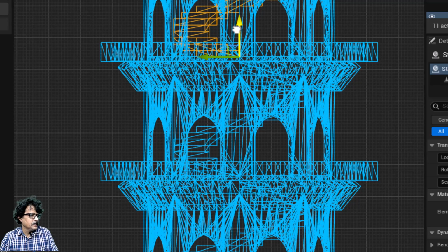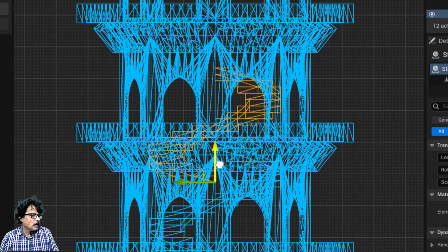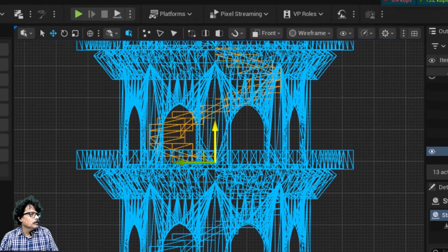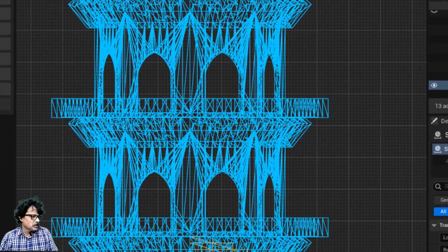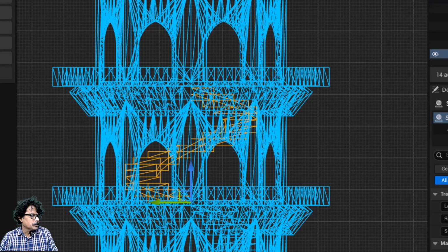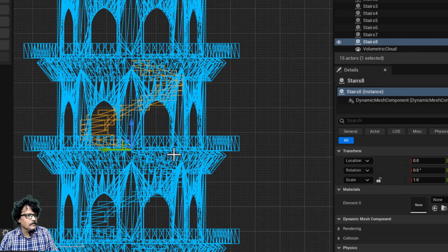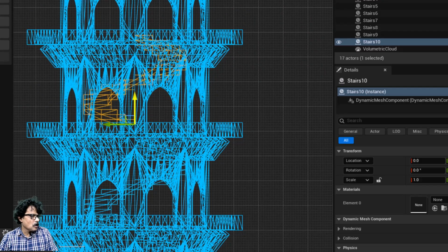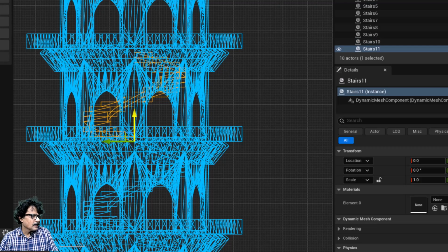It will come from here. Okay. So, now I will right click, move up, Alt and move it up and create stairs 5, Alt click and move it to the top to create stair 6, and then I will just repeat this, Alt and move it to the top, stair 7, then Alt and move it to stairs 8. We could have used pattern and created it. I will move it up and move again, stairs 10. So, I will just Alt drag and precisely place it on every floor like this.